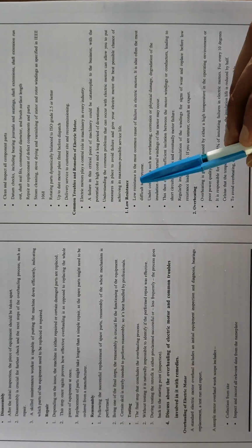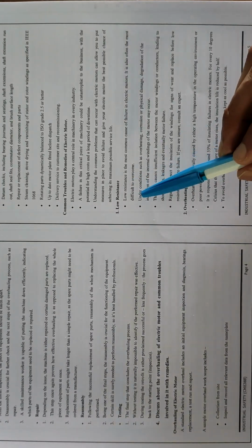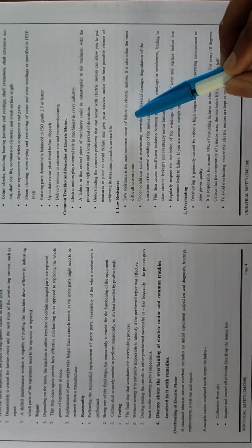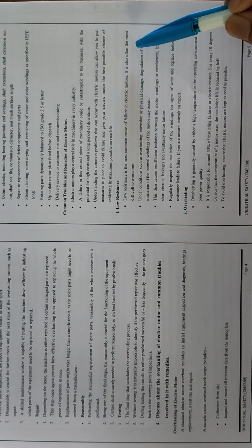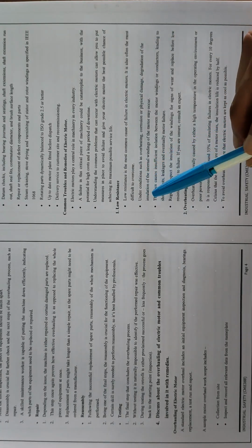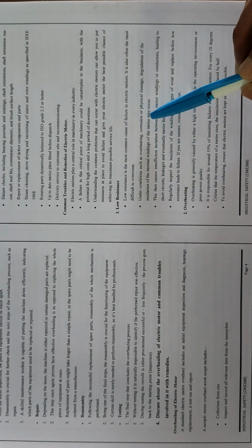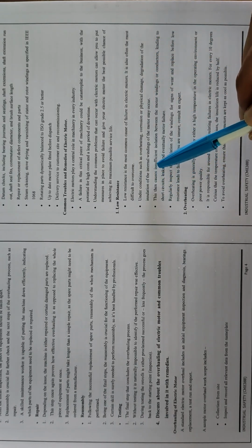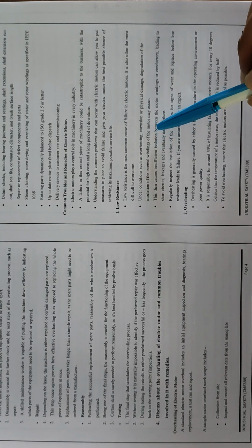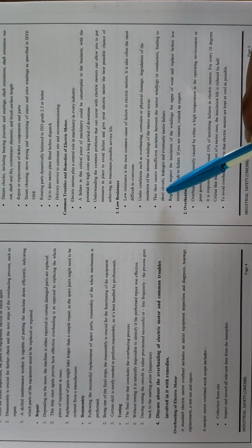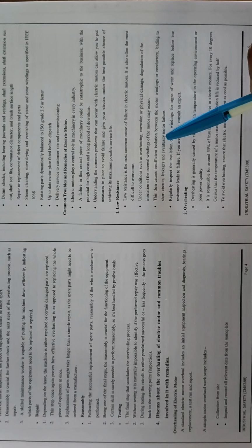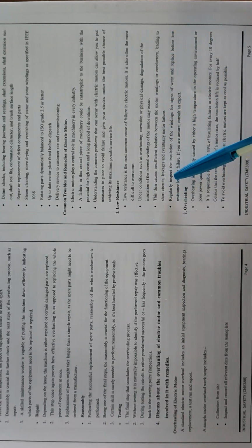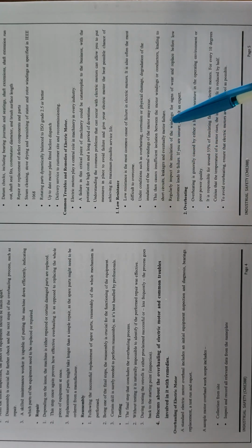Low resistance. Low resistance is the most common cause of failure in electric motors. It is also often the most difficult to overcome under conditions such as overheating, corrosion or physical damage. Degradation of the insulation of the internal windings of the motor may occur, and this then causes insufficient isolation between motor windings or conductors, leading to short circuits, leakages and eventually motor failure.